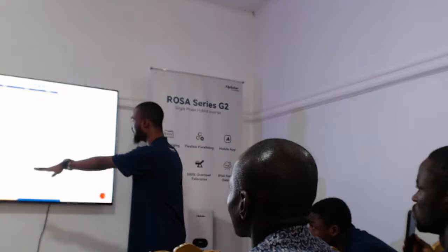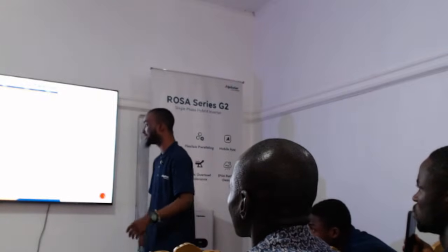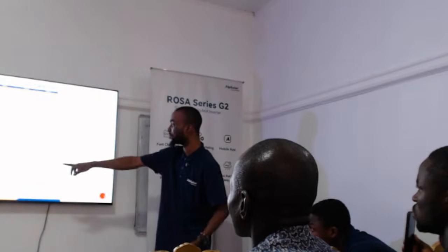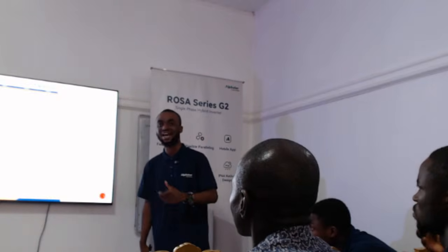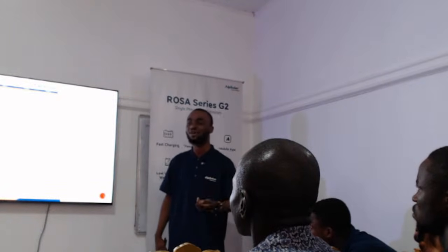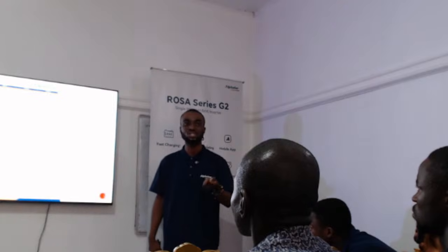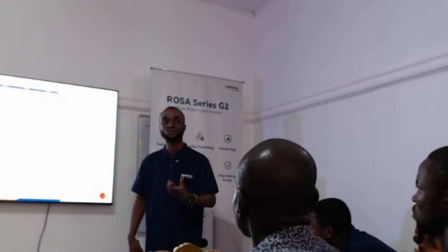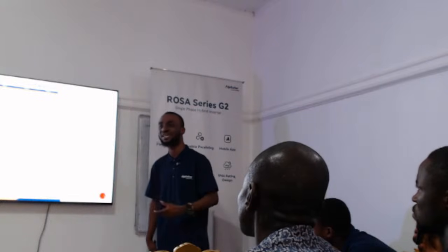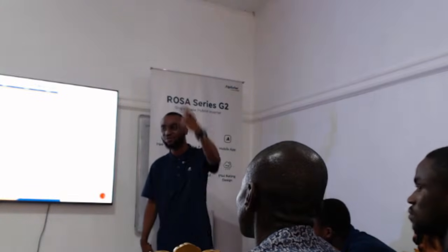These are the dimensions in width, in height, and in depth, and the weight is 39 kilograms. It is transformerless, but it has a feature called LLC, that is, double inductor capacitance. It's a resonance converter. The function of that LLC is to ensure that there's a safe charging from the PV to the battery.